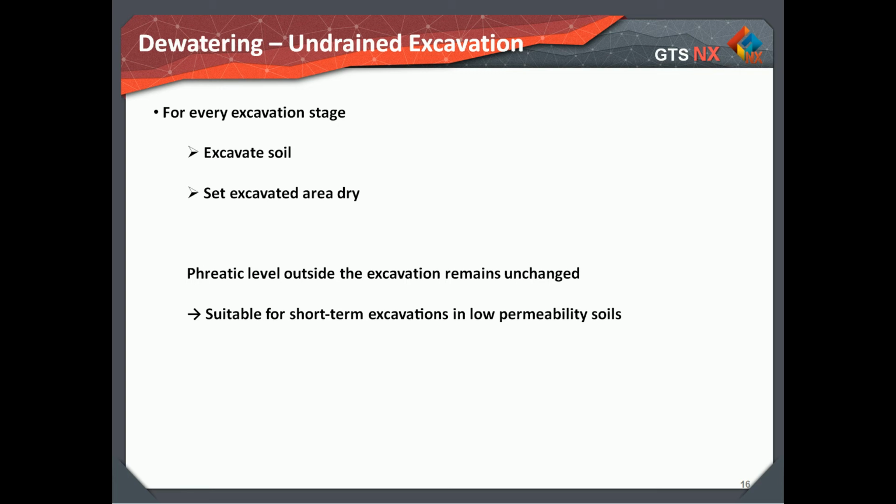For every excavation stage, in case of undrained excavation, firstly excavate soil and then set the excavated area to dry condition. And the piezometric level outside the excavation remains unchanged, therefore suitable for short-term excavations in low permeability soils.